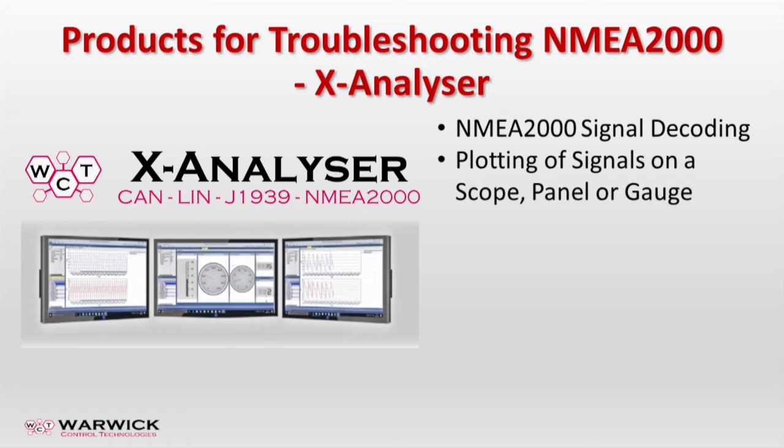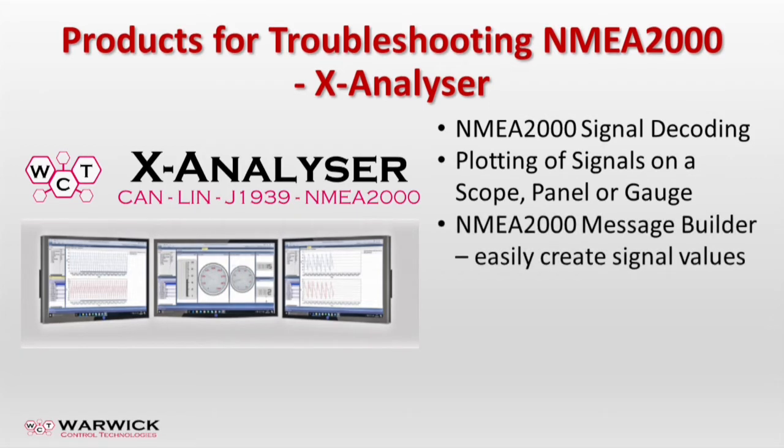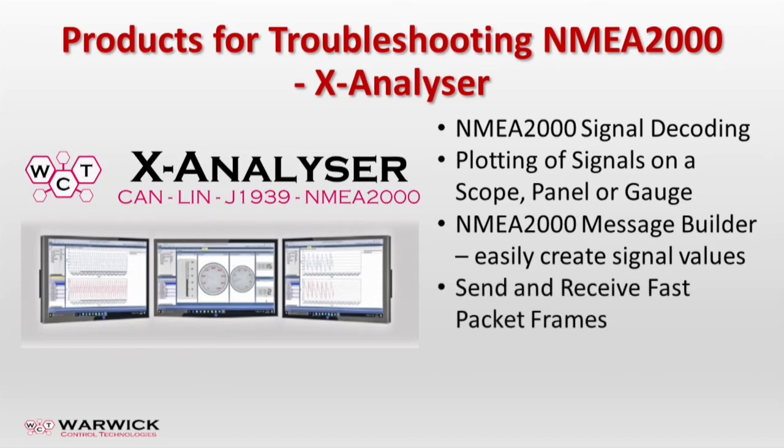A new X-Analyzer 3 feature is the NMEA2000 Message Builder, where CAN messages can be created by entering the wanted signal value, i.e. water speed equals 10 meters a second, rather than translating hexadecimal byte values. X-Analyzer can send fast packet frames from the NMEA2000 protocol from the object transmitter, as well as receive and decode fast packet frames.